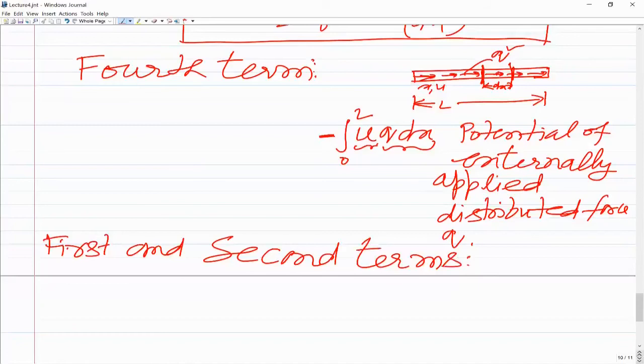For the development of finite element level governing equations, we will most of the time directly use the integral functional, consisting of strain energy and the potential of applied forces. So we should be able to write the integral functional, or total potential energy, directly.